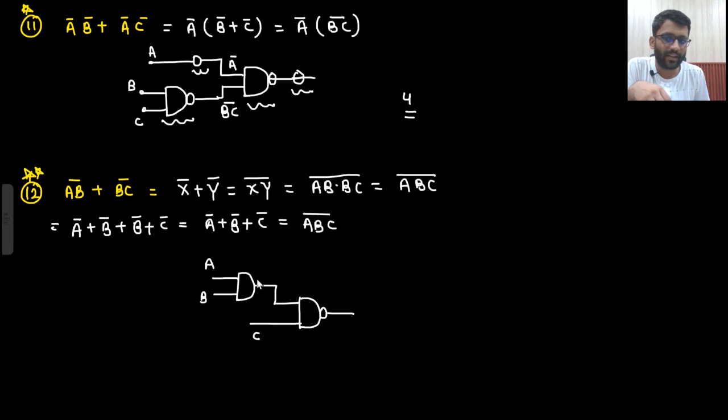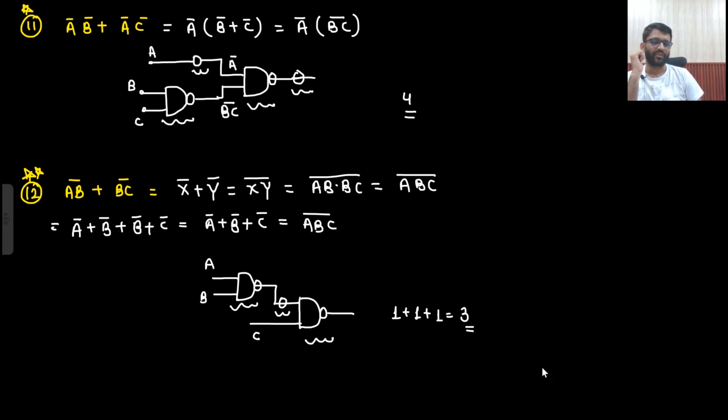So this is what I want, AB into C. This is already an AND gate. To make this a NAND gate, I need to use one inverter. So another inverter I will introduce. So 1, 2, and 3. Answer is 1 plus 1 plus 1. That is 3. So in this way you can proceed. More interesting examples will come. This one. What can you do about it?